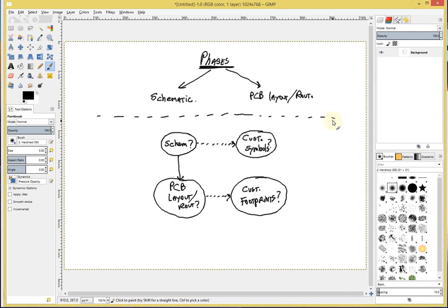Some programs allow the footprint creation and the pad creation to be part of one program, but in OrCAD this is actually done in a separate program called Pad Stack Designer. That means that before you can create footprints, you have to have designed your own pad stacks, the pad files that you will be using.